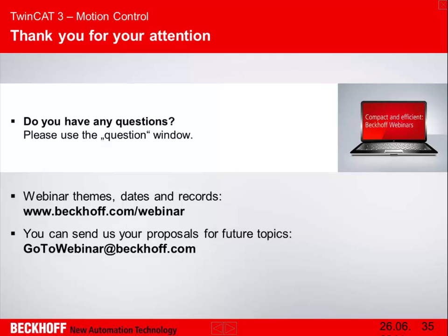There's one question regarding touch probe functionality. So the touch probe functionality can be used in different environments. So touch probe can be used, of course, with the touch probe inputs on the drive, but we can also use touch probe with special terminals, so normally timestamp terminals, which is then a distributed touch probe application.